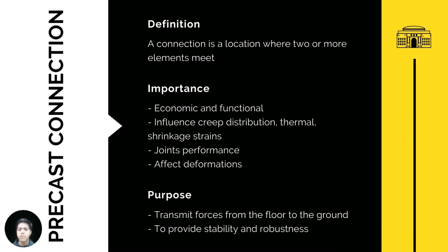There are two purposes. The first one is to transmit forces from the floor to the ground, because the load from the floor needs to be distributed carefully, or else it will cause future problems. The second one is to provide stability or robustness of the floor.